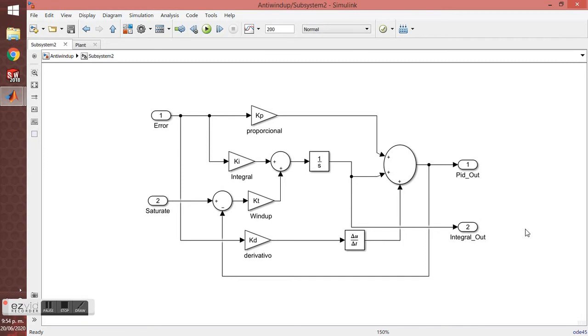To prevent this phenomenon from happening, there are two ways. First, introduce limiters in the variations of the reference such that the output of the controller never reaches actuator limits. This often produces limits on controlled operation and does not prevent windup caused by disturbances. Second, another way is the recalculation of the integral when the output is saturated, that is the diagram. The integral is recalculated such that its new value provides an output at the saturation limit. This last case is going to be our objective.